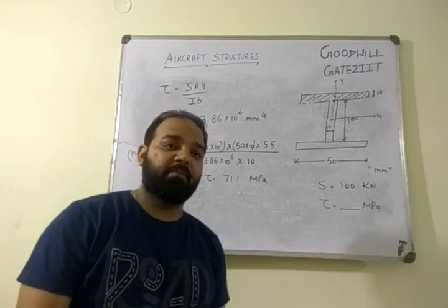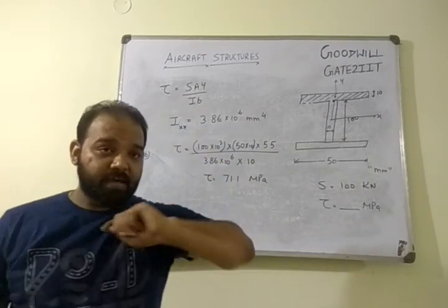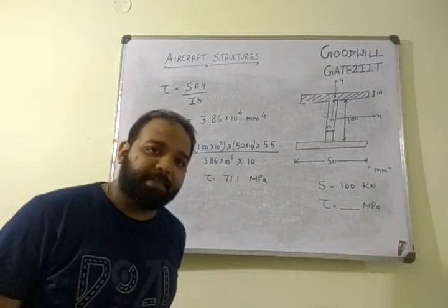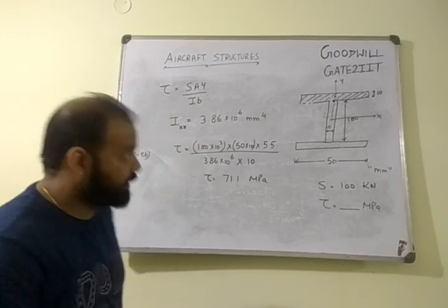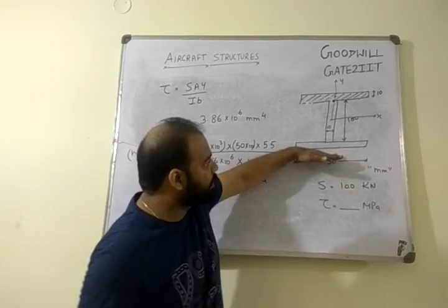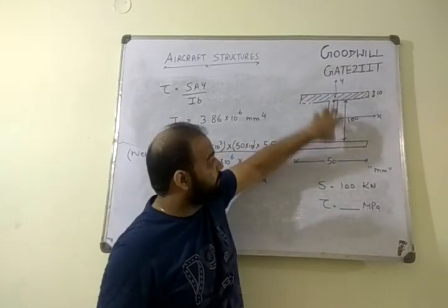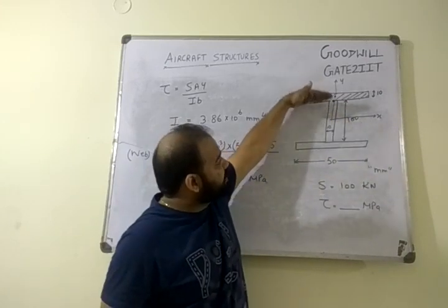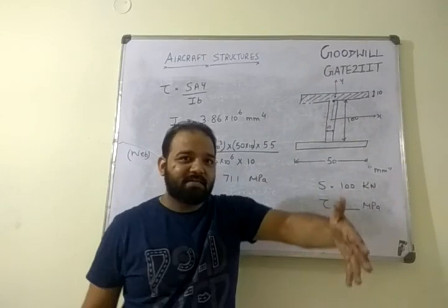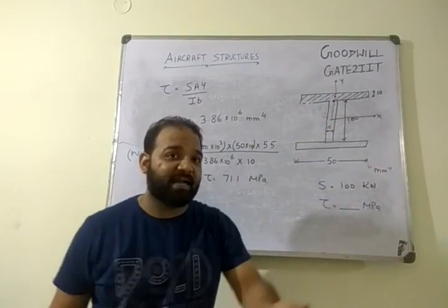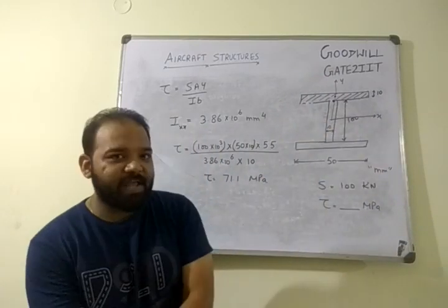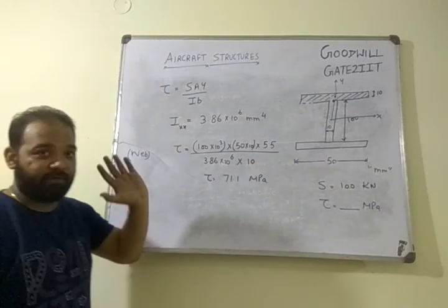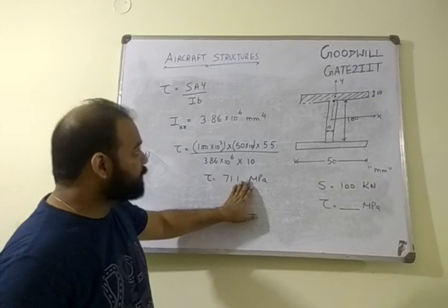Please try out this exercise. This will make you comfortable with this shortcut method. In your exams, we should always take a call in which we can skip more calculations. For example, if I would have shaded the lower portion till this point, right? I have an additional work of calculating CG. But if I move from up point till this point, I know it is a rectangle, area is simple, length into breadth, and CG is exactly at the center. So this call we need to take in your exams. That should I move from top surface or should I move from bottom surface? At practice level, we have moved from top.